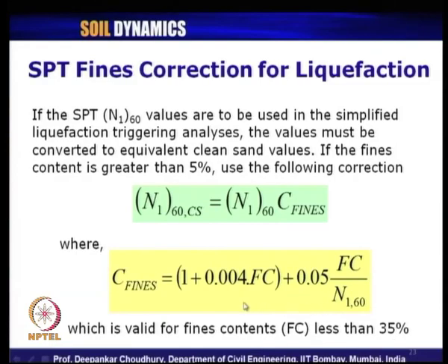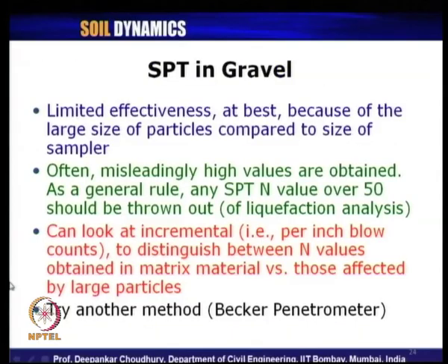So, this equation we should use to find out the correction factor with respect to fines for an amount of fines between 5 to 35%. Now, sometimes the standard penetration test is also used for gravels, though it is very good for sandy type of soil mostly.